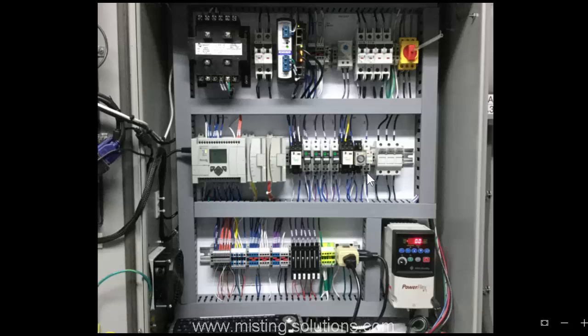And what that relay does, that 3-second relay, is it energizes zone 4 solenoid valves. It energizes those valves so any high pressure water that is left over in zone 1, because that's the last one that was on, is dumped into zone 4, and then once it's dumped into zone 4 and the 3 seconds are over with, the normally open solenoid valve, the dump side of zone 4, opens up and then dumps that residual to drain. So it is kind of a sneaky way of dumping the high pressure water that's left over in the piping of the system before the zone valves.